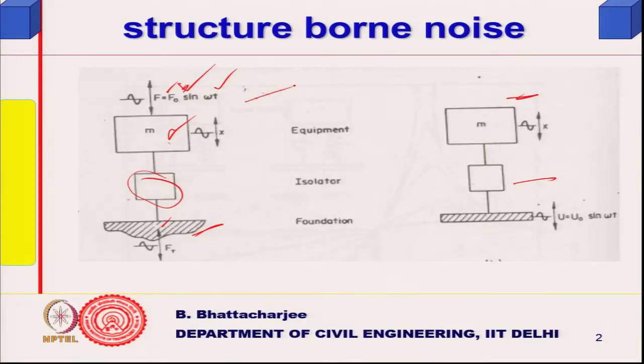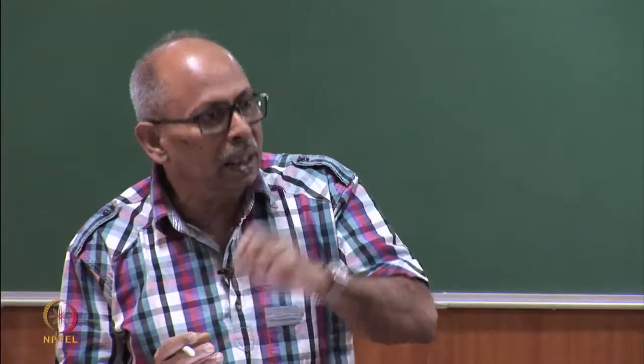Let us say I do not have the forcing function now and I have put the isolators, the mass would be there. This mass results in some static deformation or static deflection of the isolator itself, which might be something like a spring, or a similar sort of system. The idea is that a spring will store the energy and release it.